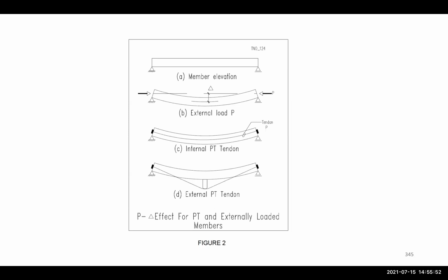It is not considered an external force. It's considered an internal force, like an internal system. It's part of the system. The PT cables and the force are part of the system as a whole. It's not an applied force from outside. So that's why typically we don't consider that. Okay.